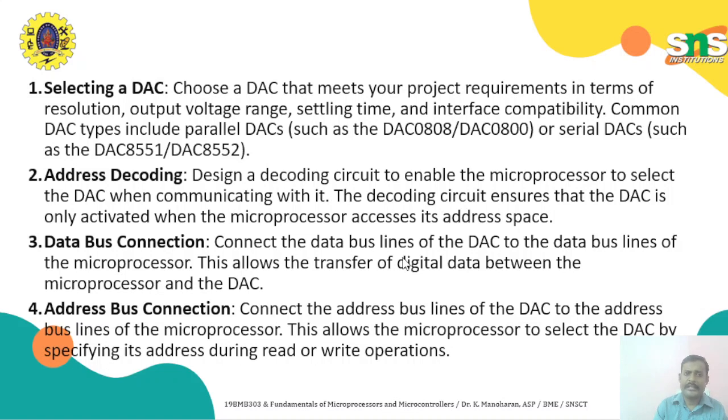Selecting the DAC, so choosing the DAC will be important. Depending on the application we can choose it. We can use a DAC 0808 or a 0800, or a serial DAC such as DAC 8551 or DAC 8552. Depending upon our application, we can select the DAC.